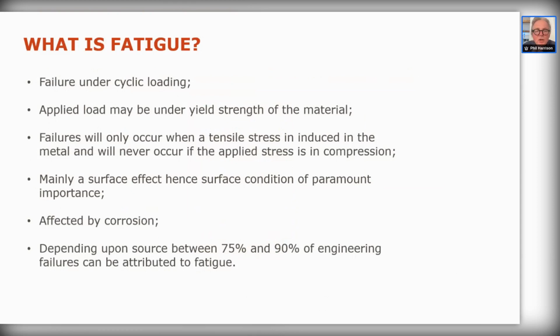The load is generally under the yield strength of the material. Because if the material yields, it will not start cracking. It'll start reducing cross-sectional area, but you will not be building up enough strain energy in the material to actually cause the fatigue crack to extend.